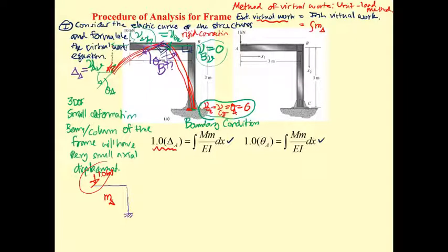It's going to have the change in the slope of the frame. So it's M times theta. And as you may know, for the deflection we have dv by dx equal to slope, and then d square v by dx square equal to curvature. And now we may rewrite this as d by dx, and you may put this for dv by dx, and that is going to equal M over EI.